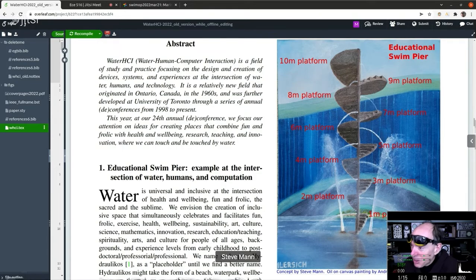So you can put your finger over that water jet and attempt to block it. When you do, you can feel what deadheading 9 meters of head feels like. It's a good physiotherapy exercise, actually putting your fingers over the water jet. And so that is an example of a teach beach feature that teaches us the interplay between head and height,